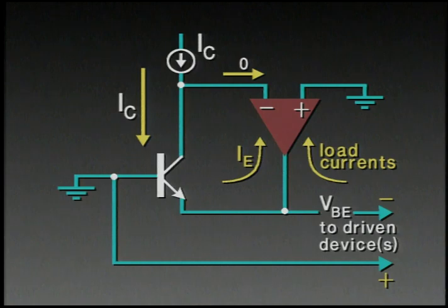A yet further way of driving the so-called translinear device would be to use an operational amplifier. This is commonly done in high-precision circuits, obviously not so commonly done, rarely done in fact, in high-speed circuits. Nevertheless, it is an important modality, and we need to be sure that we understand what's going on here. In this case, we can assume that the bias current at the input of the operational amplifier is really very small. It can be picoamps quite readily. In fact, that could be an MOS operational amplifier, and that might be commonly employed in a BiCMOS environment, for example.